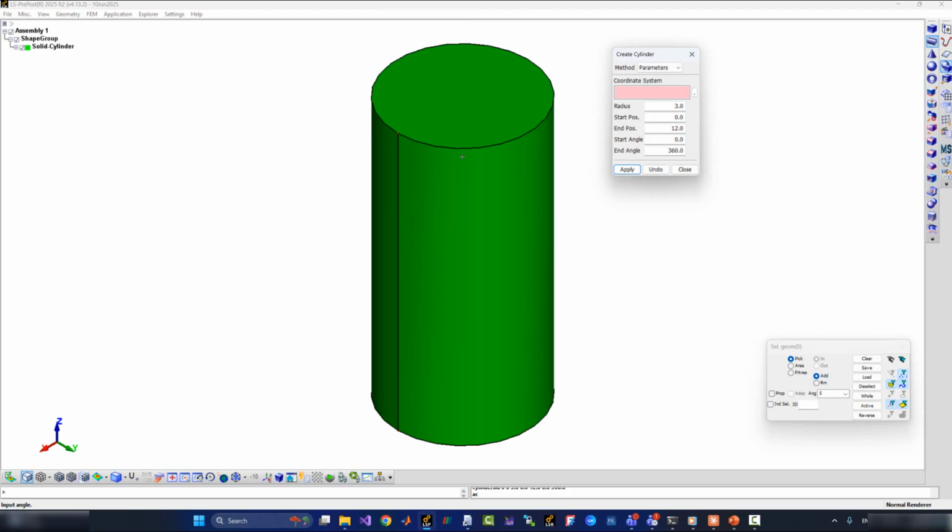So this means we must be at a location of x equals y both equal to -4.5 for one corner of the square section. The other corner must be at x and y both equal to +4.5, and then we have to give a height, a thickness along the z-axis equal to 2 inches for the bottom plate.